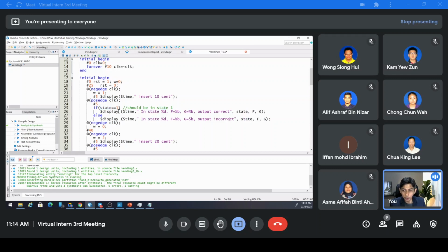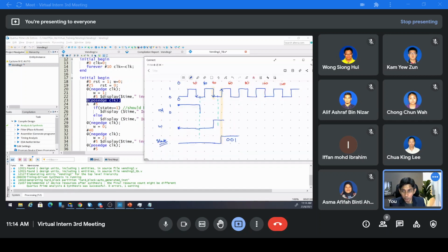So when to check? After this, we look at the positive edge. Where we are here, we are at next edge plus 5 nano. Next edge plus 5 must be 45, and the next positive edge should be this one, and we go another 5 nano to be safe.